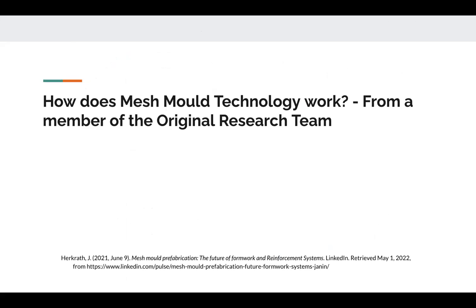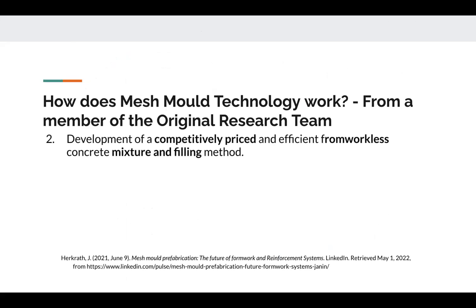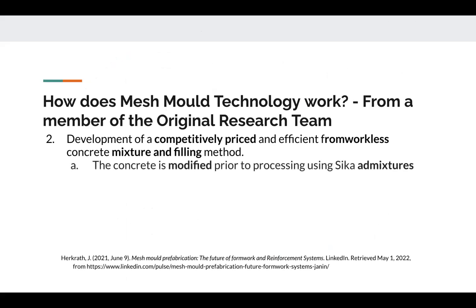How does mesh mold technology work, continued. This would be number 2. They developed a competitively priced and efficient formworkless concrete mixture and filling method. So not only are we mixing it, but we're filling it to provide a complete structure. The concrete is modified prior to processing using silica admixtures.